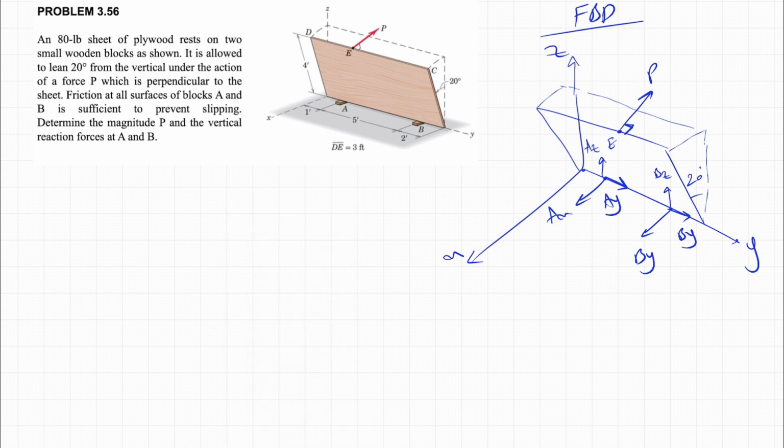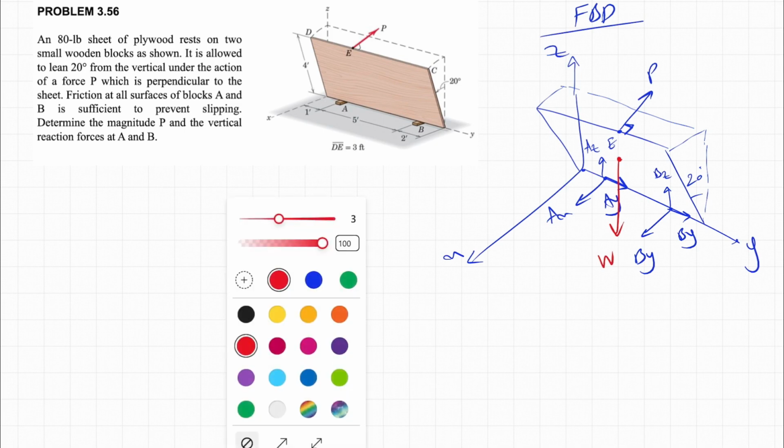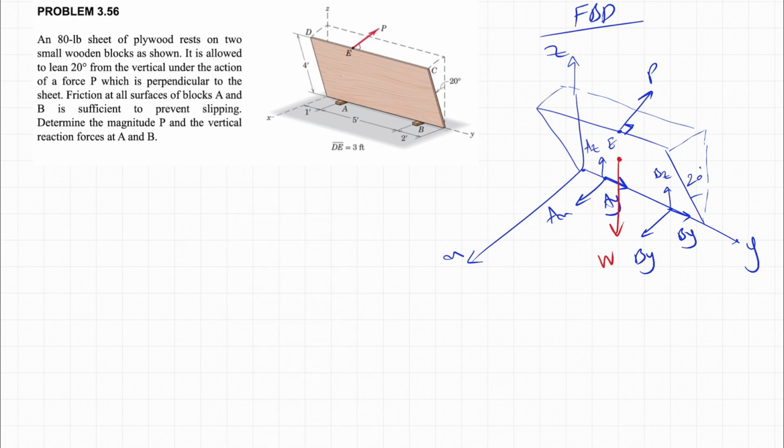There is one more force, and that would be the weight of the sheet, which we know will be at the center of the sheet. Let's call it W. And that's pretty much all the forces that we have. Let's just write everything down in vector form.